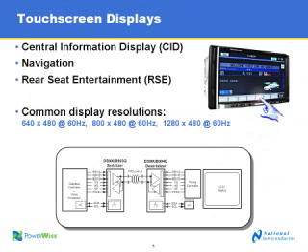Now at the same time, the graphics controller is able to read touchscreen information from the display side, and that's where the I2C and bidirectional control come into play. And that's really the difference with these new chipsets. Exactly. Now we're sending all this control over the same set of wires that we're sending the video. So there's no need for a separate control channel between the host side and the display.